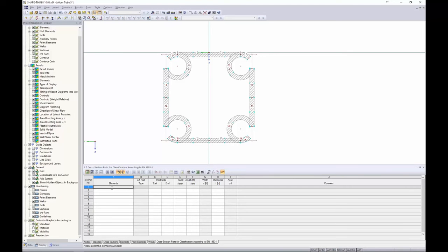So I'll begin with the left side with element 4 and 14. And the restraints, I want to check these both as restrained. This is a closed shape. Now, if this arc didn't exist and this was an open end here, then we would want to leave this as unrestrained. So that's important because when it comes to aluminum design, it depends on how the local buckling is checked.